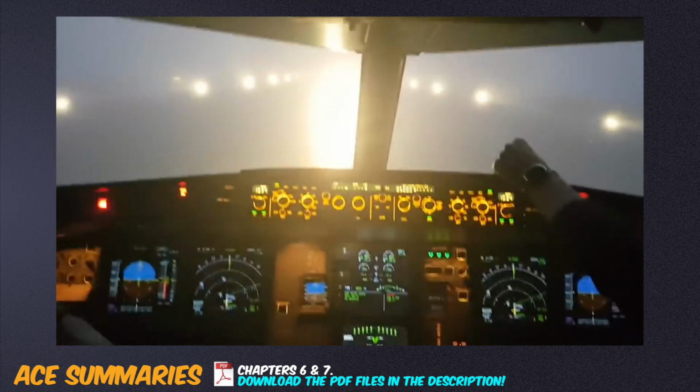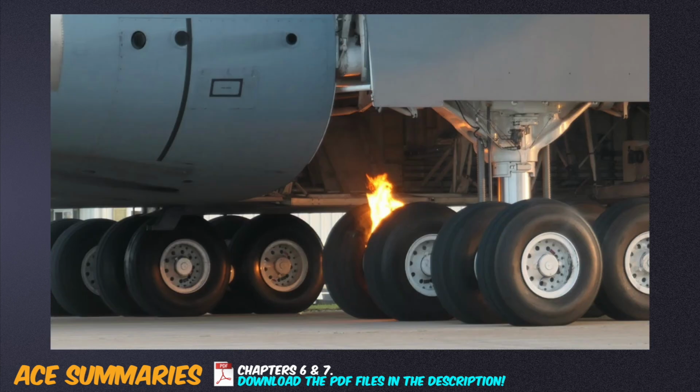immediately after touchdown. Tire temperature before the takeoff run also depends on taxi time, aircraft weight, outside air temperature, and amount of braking used, because heat is transferred from the brakes to the tires themselves. Brake temperature must be below a certain limit before beginning the takeoff run to account for the possibility that the takeoff may be aborted before V1, ensuring the brakes will function properly and not exceed any limitations.